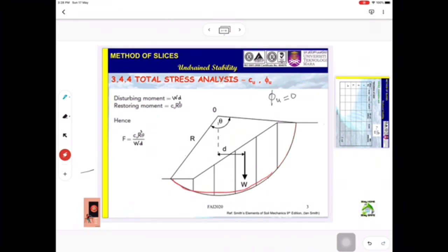This is the outline where the slip failure plane occurs, and let's say this is A and this is B. So this is a sector AOB. In the mass procedure I explained last week, you determine the mass for this whole section without making it into a few slices.